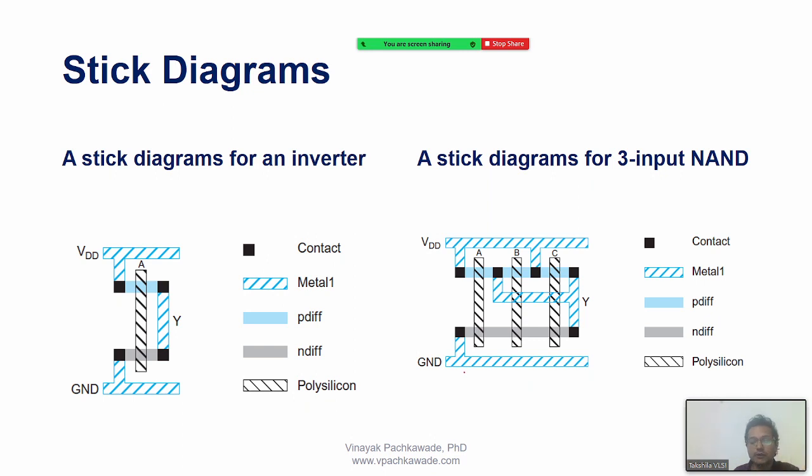To have a rough estimate, to draw roughly the layout of any cell, and also to have an approximate area that will be required for my chip based on the design rules, layout engineers will often use the concept called stick diagram. This is there in your syllabus also.